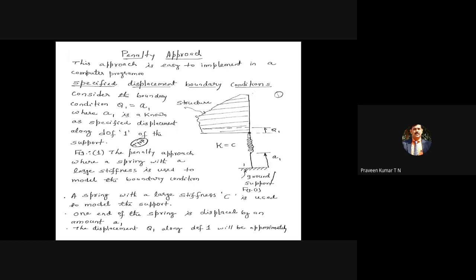Instead of moving the fan in the downward direction by 10 mm, because steel wires are slightly stronger, it may be moved by a small amount, 5 mm. Instead of a steel wire, you can rigidly mount the fan by a nut and bolt system. Then the deformation may be very, very small. Instead of 10 mm or 5 mm, the displacement of that particular point, one end of the fan, may be only 1 mm or 0.1 mm.